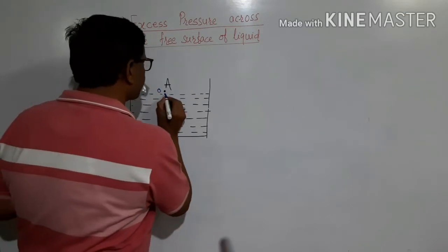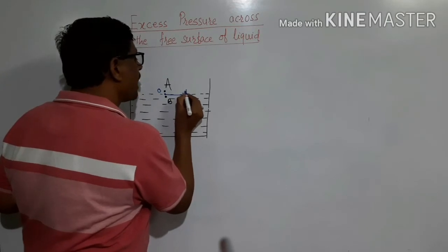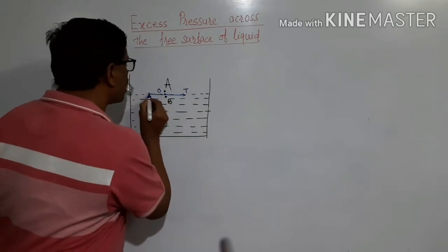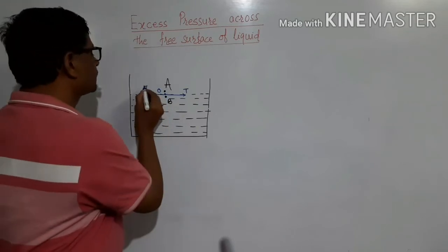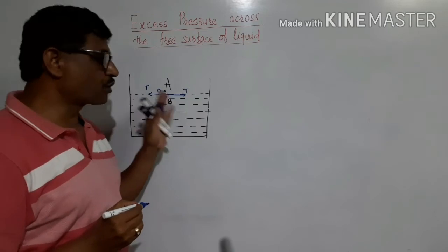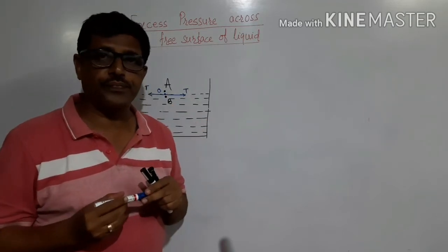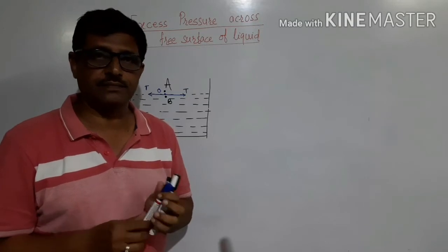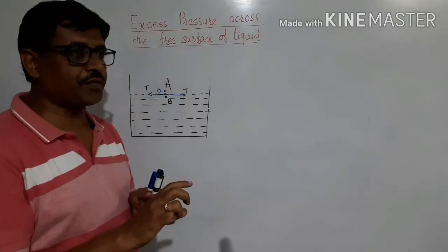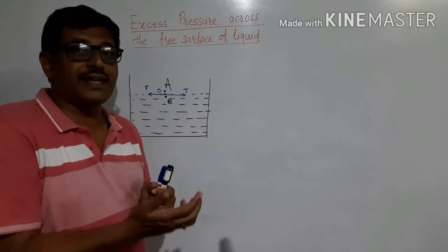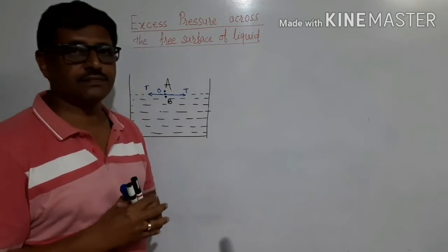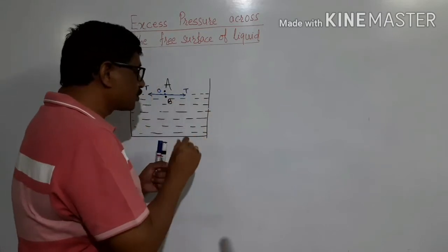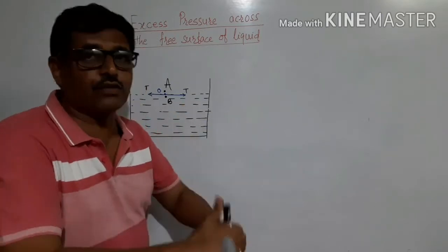At point O, a force of surface tension act tangential to the liquid surface from all sides. Therefore, the force of surface tension acting at point O acts from all sides and cancels each other. Therefore, the force of surface tension is not able to produce any excess of pressure, or rather, as the force of surface tension is horizontal, it does not have any vertical component acting on the surface.